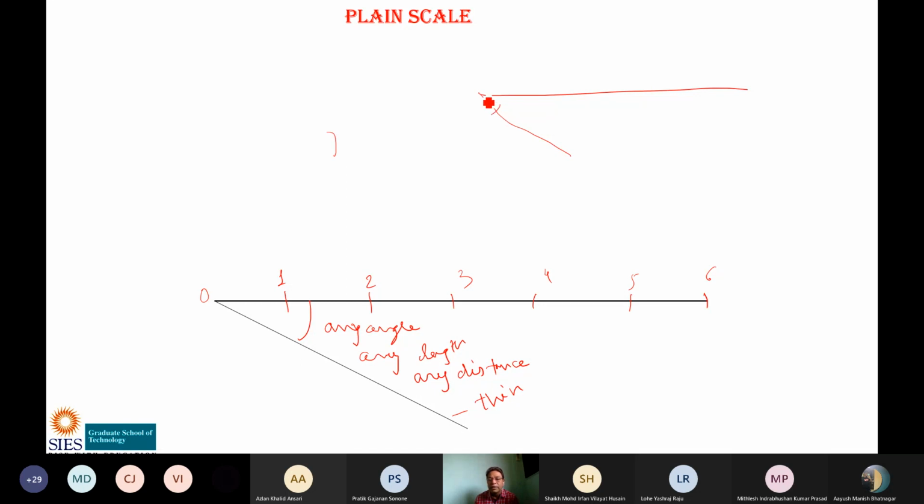One arc, keeping one leg of the compass here. I have drawn one arc. Then keeping one leg of the compass here, a second arc, third arc, fourth arc, fifth arc. I am extending it, and the sixth arc. Why 6 arcs? Because how many points do I want? 6. So this is 1, 2, 3, 4, 5, 6. Students, count it like this. This is 0, so this is the first arc, second arc.